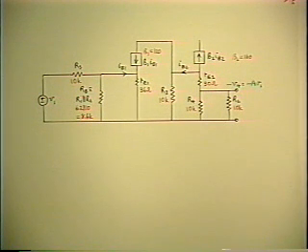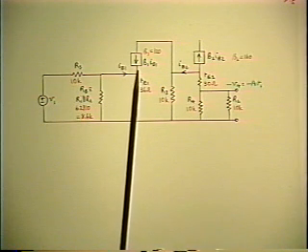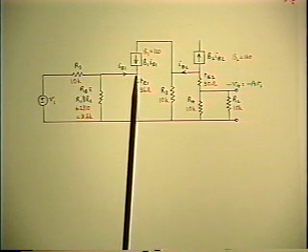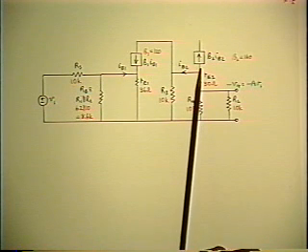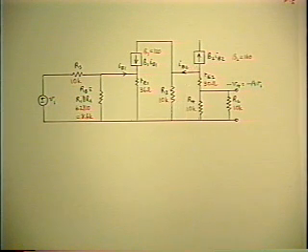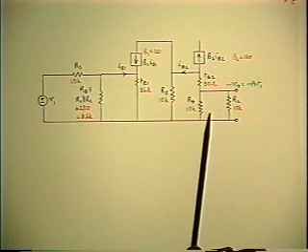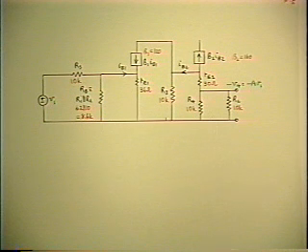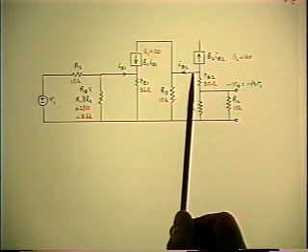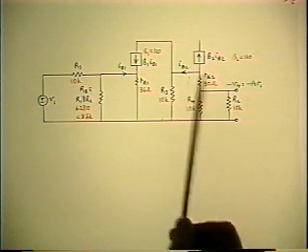As a passing comment, notice that the model of the first transistor is the one we've used all the time. The model of the second one is the same, but the current direction arrows are reversed. That does not mean it's a PNP transistor instead of an NPN. It isn't. They're both NPNs, as you saw in the original model. The direction of the arrows is arbitrary because this is a small signal AC model anyway, and you can choose whatever reference direction you like. The only requirement is that you have consistent directions between the dependent quantity and the independent quantity.